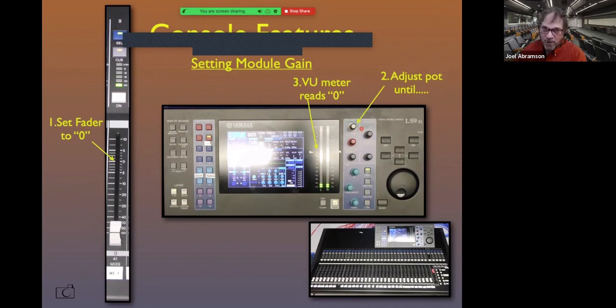potentiometer, we call them a pot, right? This trim pot, you trim it up so that the meter volume goes up to here and not past it, but right up to there. When that reads 0 and this is at 0, then you're all good and you've set the level for that, right? What other things can we do with this feature here?